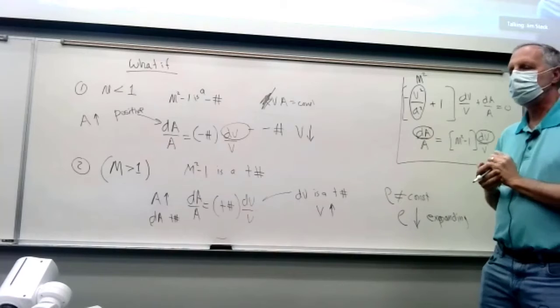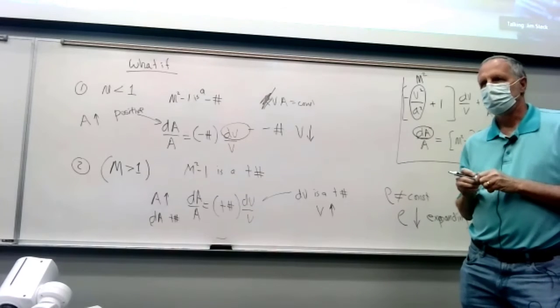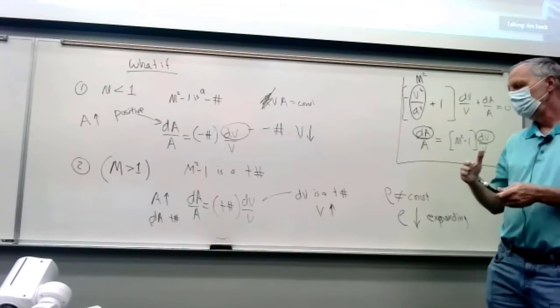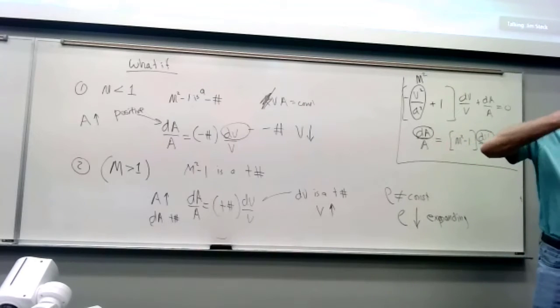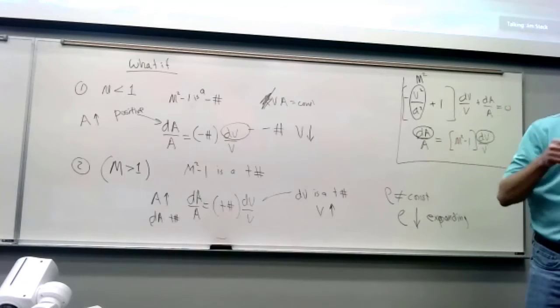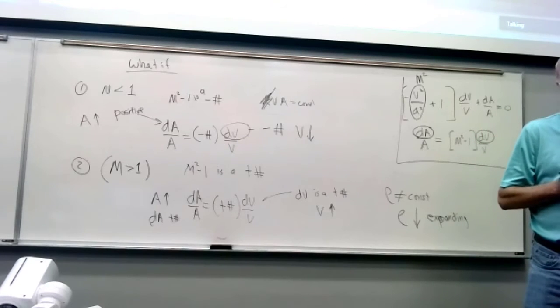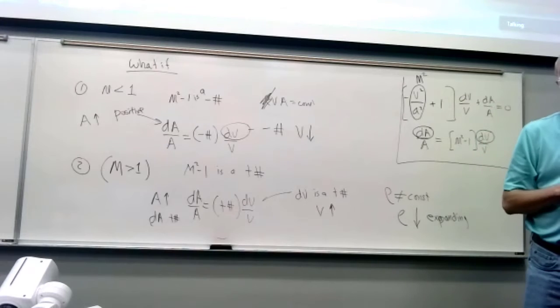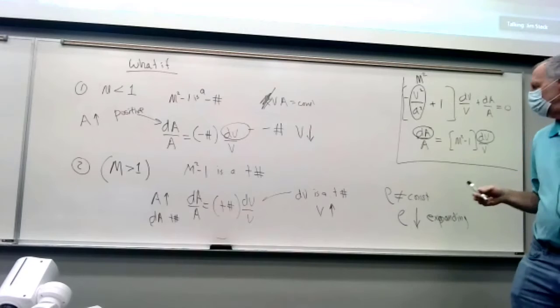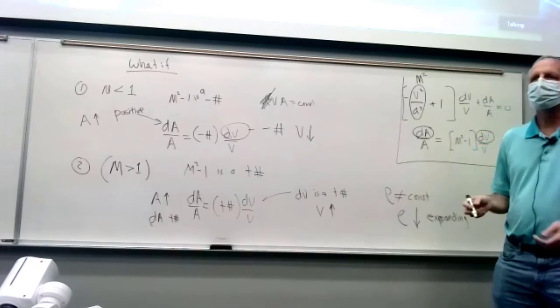The shock wave is a huge pressure jump. We'll talk about that in like a week. But it's a pressure, temperature, and density jump. So yeah, they are related. In a shock wave, you go from supersonic flow and you go through the shock wave, and the air compresses together. You get high pressure, high density, and the temperature goes up. And it slows down to subsonic flow. So really, the energy in that supersonic flow is turned into density, pressure, and temperature increases.